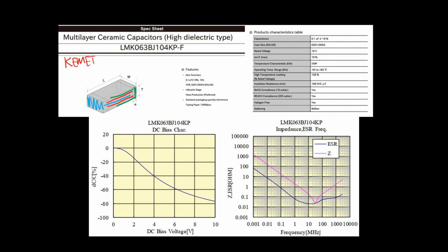Cool. So there's some temperature. It tells you the maximum operating temperature, back to thermal breakdown. And also insulation resistance, so this is like the leakage, the non-ideality of the dielectric. So there's two things I wanted to show you with this ceramic capacitor specifically. Ceramic capacitors are strong functions of applied voltage. So as the DC bias on the capacitor increases, the capacitance decreases significantly.